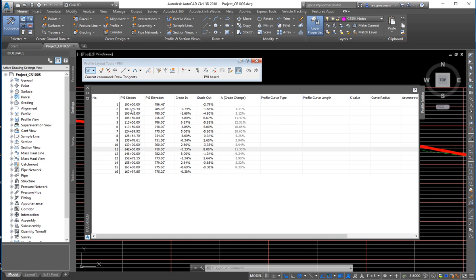Just to be making everything look nice, you want these stations to be right at an even 25 feet. Maybe 10 if you really had to do it. So this one I'm going to round this guy up to 50. I can just type it in here. And that will automatically move that PVI point for me. Oh, that's ugly. Who put that in there? Let's do 125. You can fix these visually, or you can type them in.